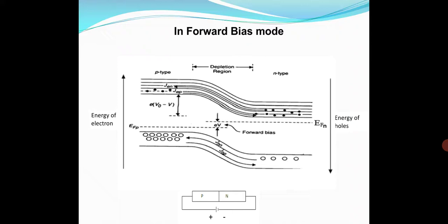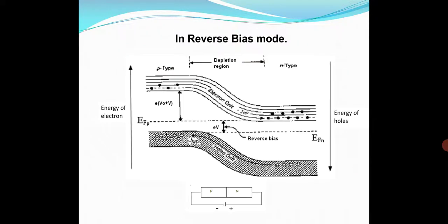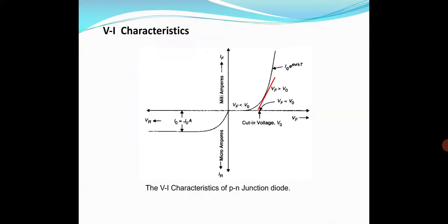In forward bias, the charges are depleted, and we get some electrons that are already present nearby. The holes will be shifted towards the valence band of the N-type material, and electrons will be shifted towards the conduction band of the P-type material. So charges will flow accordingly. Electrons and holes drift due to the applied external potential. According to that, we get the VI characteristics of the diode.